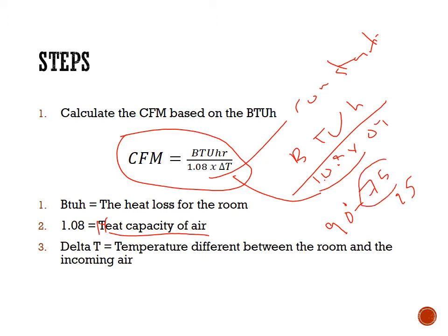So this is what you actually want, and this is what you assume as your hot air capacity. Usually it's 90 or 100. So you can put a number for your project and assume this is going to be your system. This will also vary based on the fuel you're burning, the efficiency of the system, and duct work. If you're burning oil or gas, you probably have a hotter temperature than if you're using a heat pump. So this will depend on your heat source, and this is something you pick. For your project, you can put 90 or 100, whatever you find is reasonable.